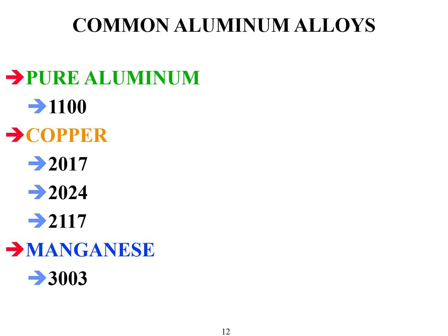However, this next alloy, which is copper, the first letter, remember, designates the primary alloying ingredient in these aluminums. 2000 series, all of them, copper is your primary. 2017 is a common rivet alloy in aluminum. 2024 is a common rivet alloy, and a 2117 is also a common rivet alloy. As a matter of fact, the 2117 aluminum in the rivets is the most commonly used.